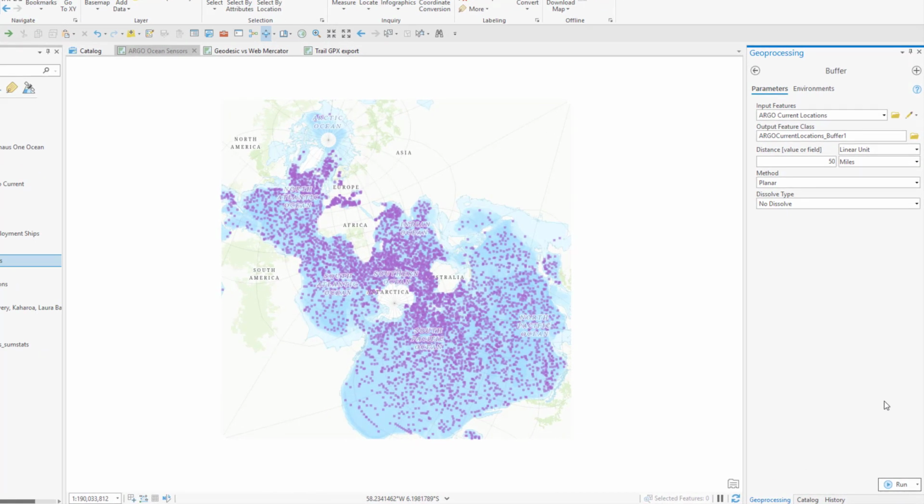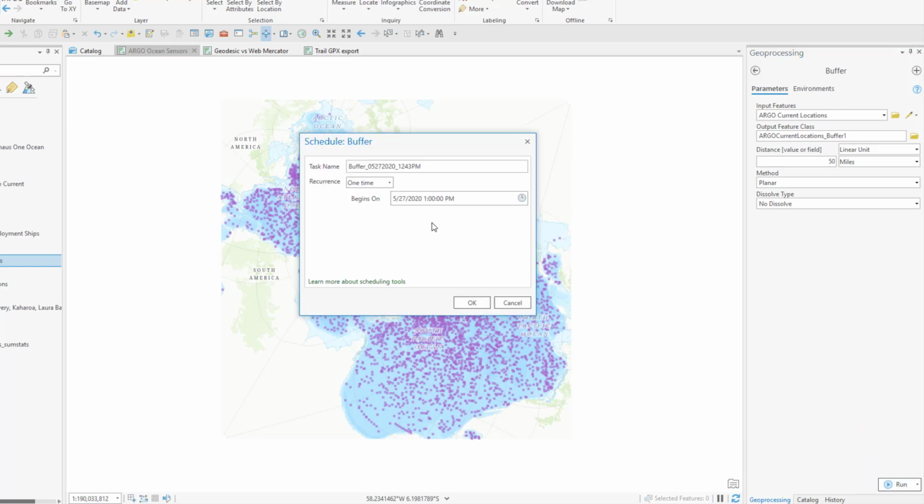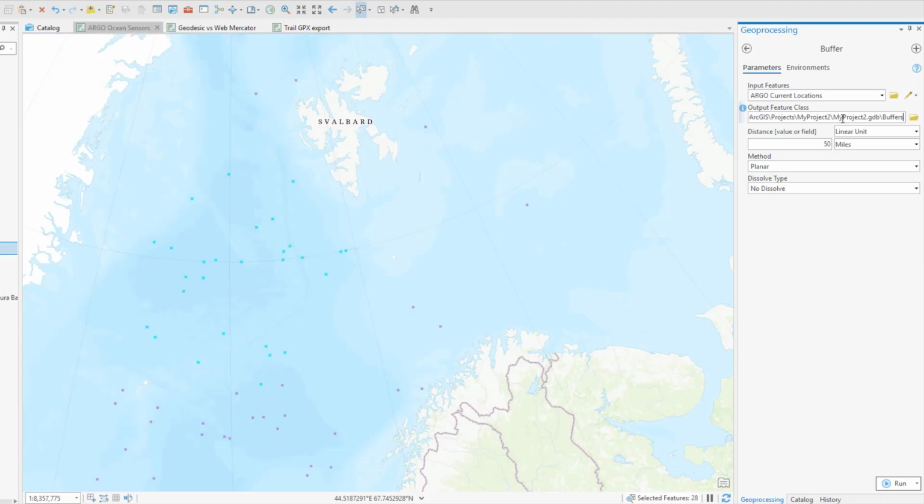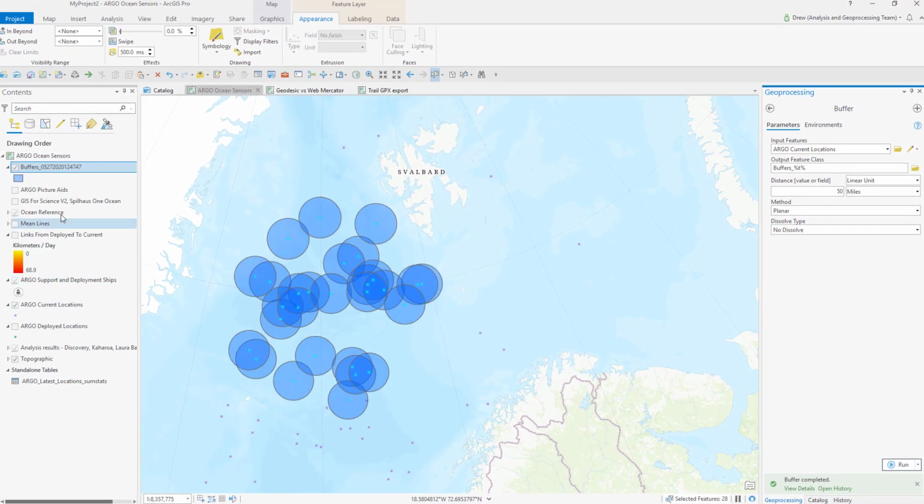We've enhanced the workflow for scheduling geoprocessing tools to run with more guidance to explain best practices for scheduling, new dialog controls for scheduling recurring operations, and new documentation sections that explain how to manage and configure scheduled geoprocessing tools. A new geoprocessing variable, %t%, allows you to include a numeric timestamp in geoprocessing output data names.